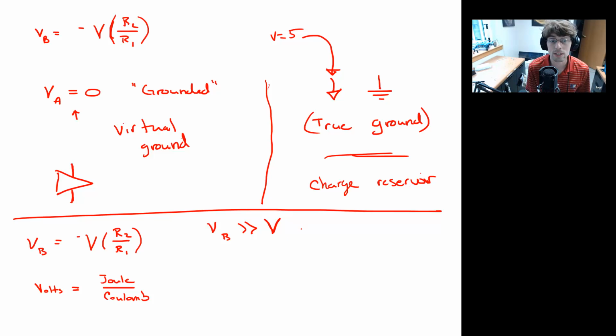Similarly, we are now seeing how we can account for the apparent violation of energy conservation. Those power inputs not only provide charge to the circuit if needed, but they can also provide additional energy. In other words, you can end up with an output potential that's much higher than the input potential. It seems like there's extra energy being created. Oh, nay, the excess energy is being delivered by the power supplies to the operational amplifier.